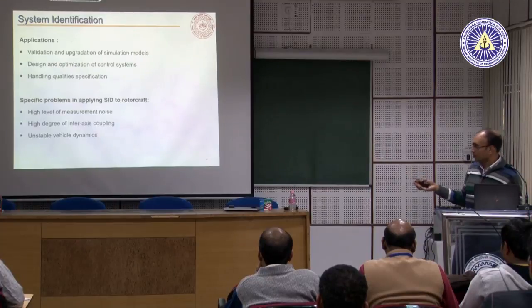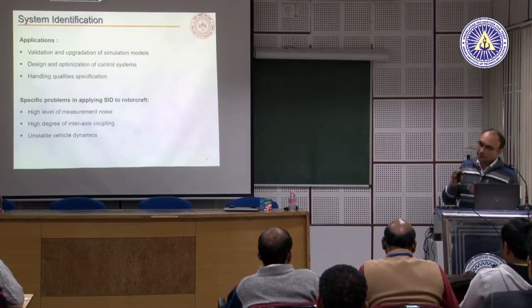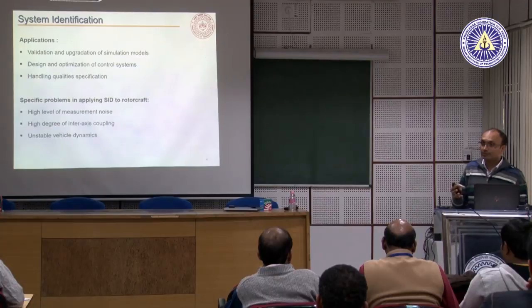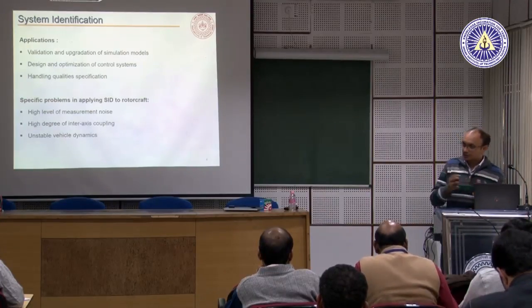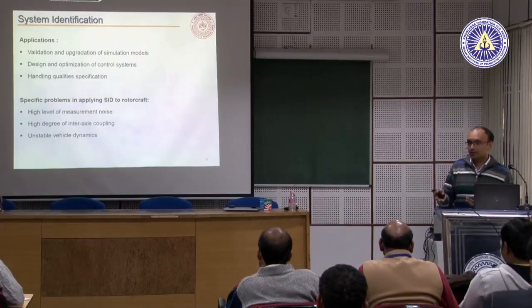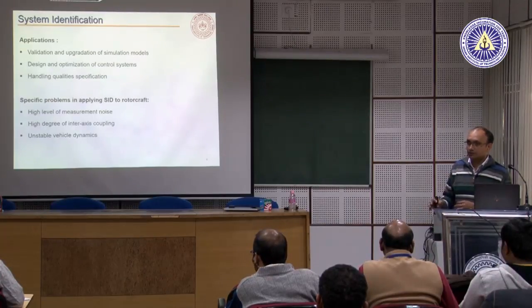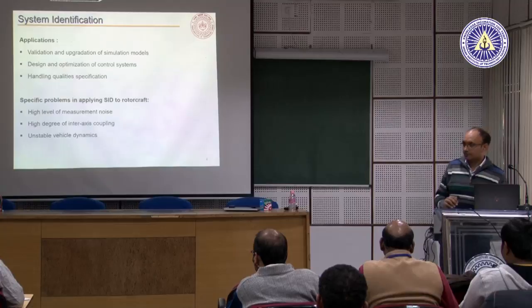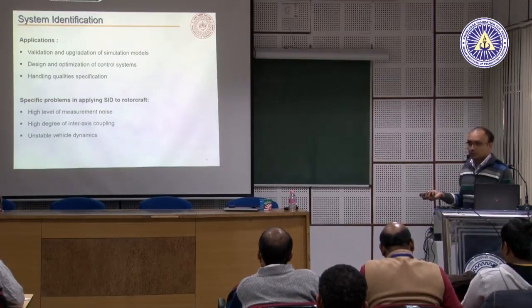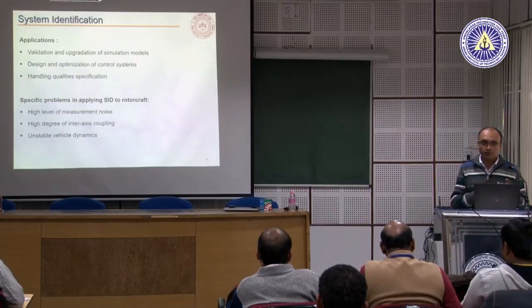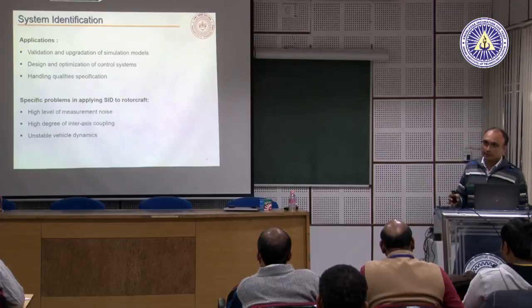So a normal helicopter without any autopilot on board, or rather some kind of stability augmentation system which we call SAS, which could be either mechanical or electronic. Without any kind of SAS, it is almost impossible to fly a helicopter. So this is another big challenge. The vehicle is unstable. So now if I want to develop a controller for a new helicopter, I am making a new helicopter and I want to develop an autopilot for that.